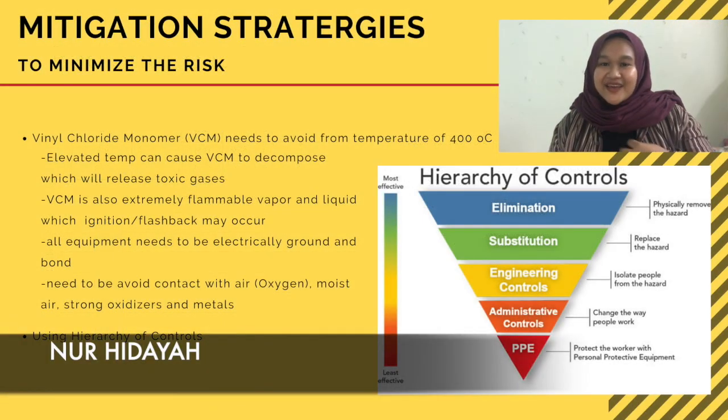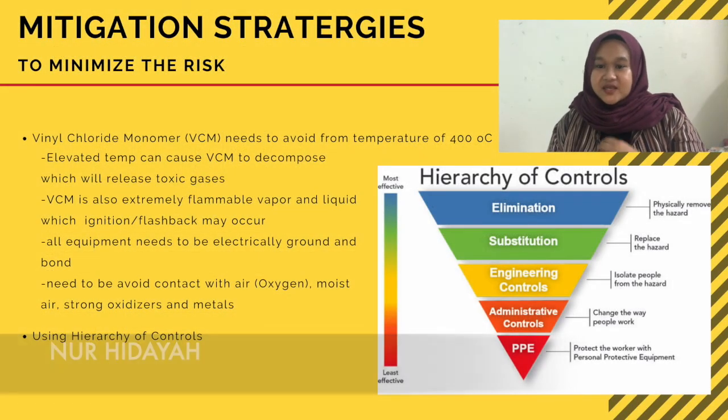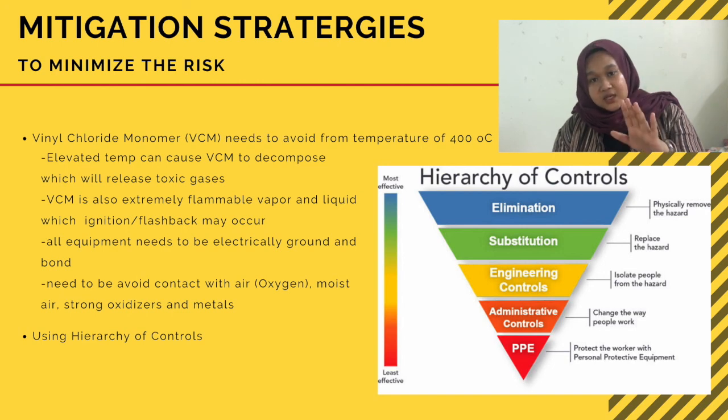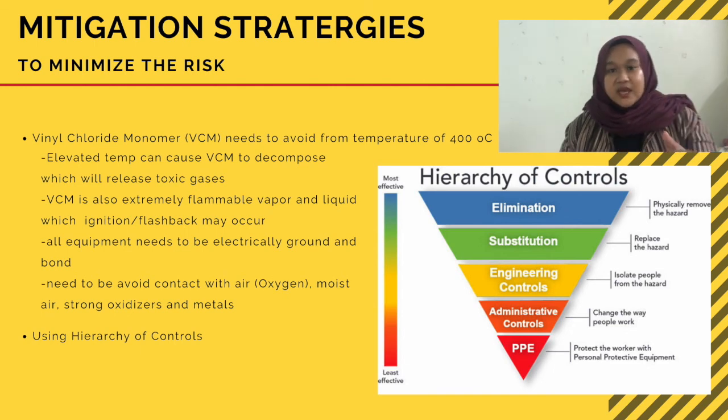Hi, I'm Nur Hidayah, and I will be presenting about mitigation strategies to minimize the risk. So VCM needs to be avoided from temperatures more than 400 degrees Celsius. This is because elevated temperature can cause VCM to decompose, which will release toxic gas, which is actually dangerous for us.